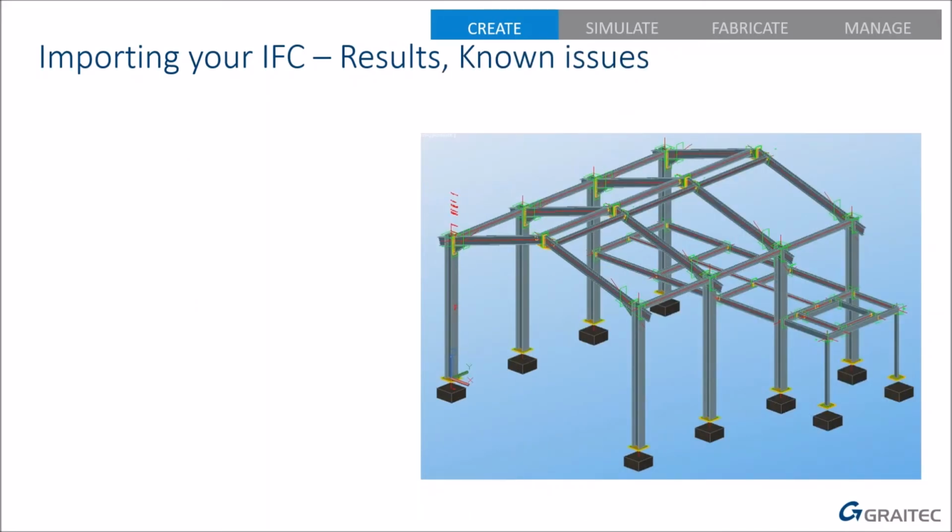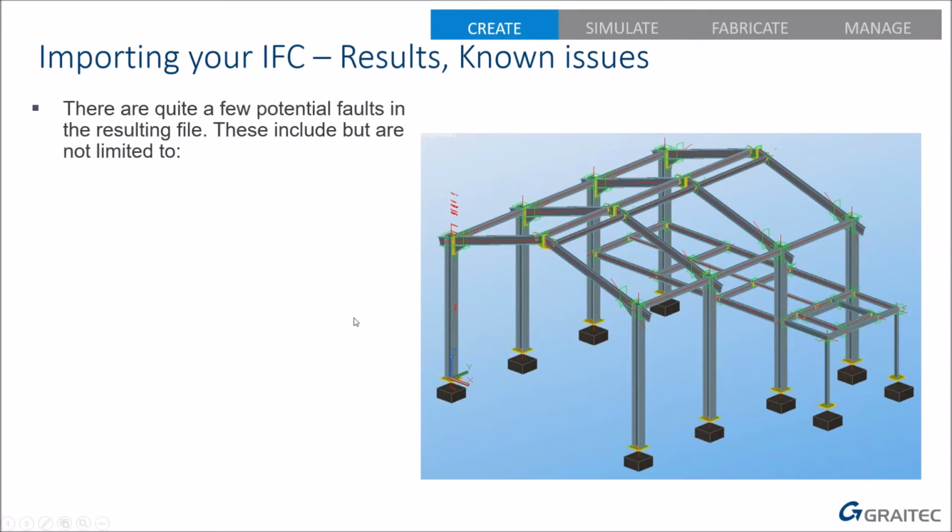There are issues with the results. There's a picture of what I just got. Some of these issues may occur every time, some of them may hardly ever occur, but there are lots of potential issues with these files that you've imported. Sections, particularly non-symmetric sections like channels or angles, can often be rotated. These issues actually often apply to any format, not just IFC. Sections can often be rotated. So user sections as well will be a classic one that will be rotated if you're not careful. But all of these came out the right way around in my model.